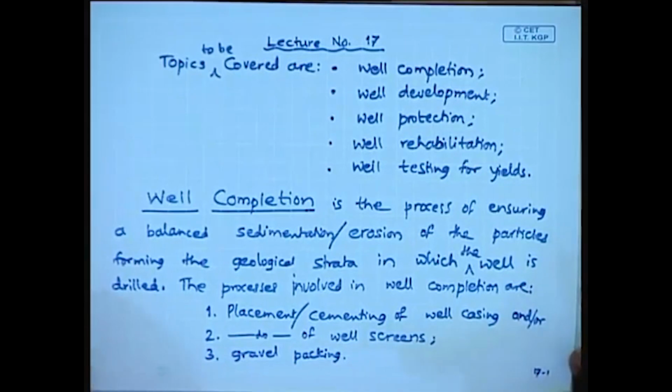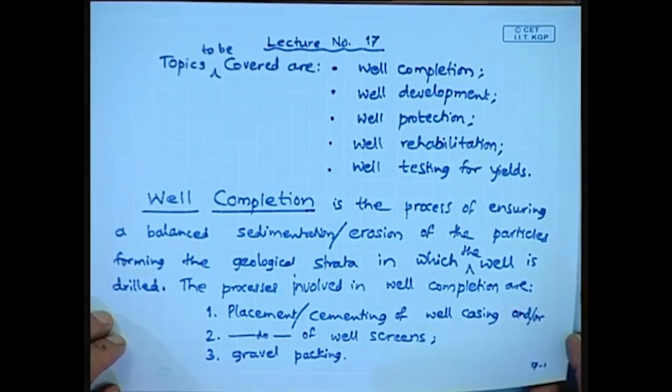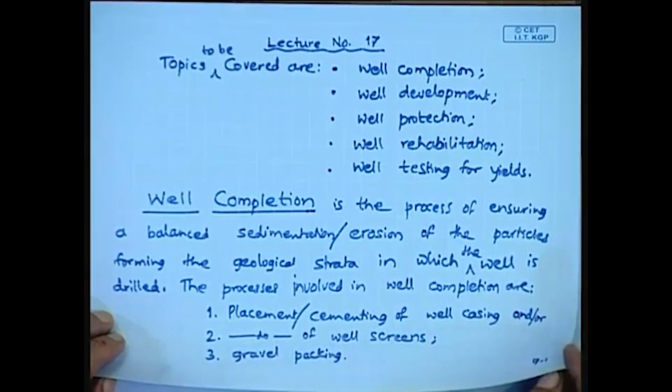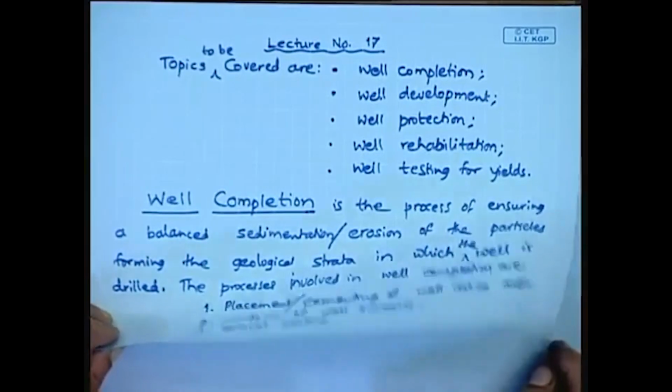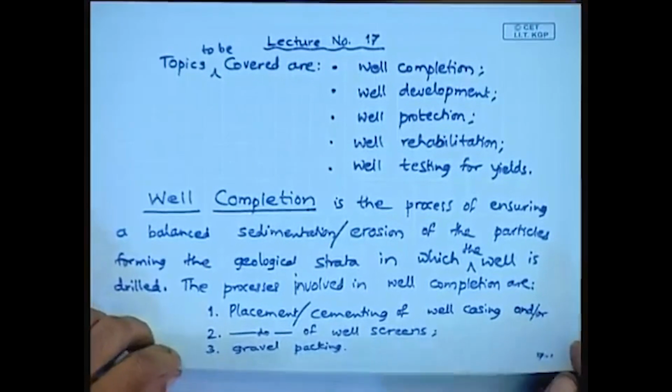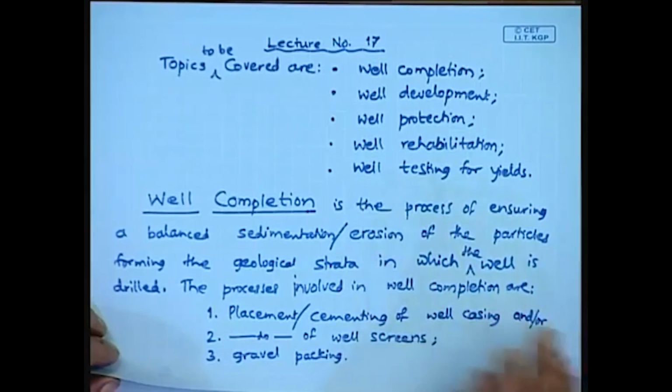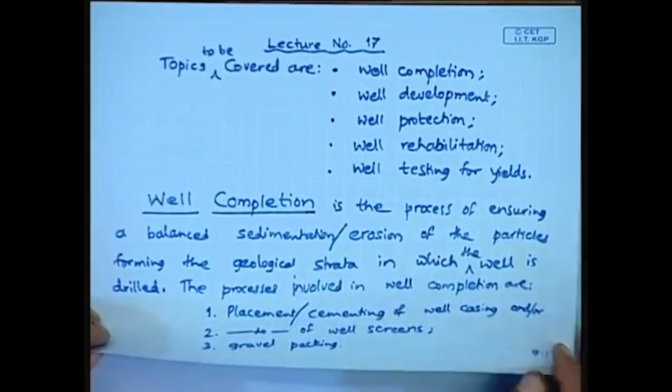Now let us briefly discuss what this well casing is, what well screens are, and what these gravel packings are, and how they help in the well completion process, wherein a balanced sedimentation or erosion is achieved so that it attains a steady state and the geological formations will remain. That is ensured. First let us discuss the well casing.